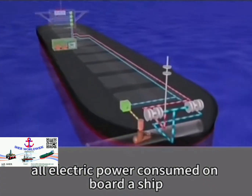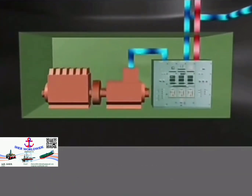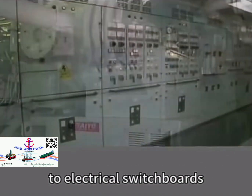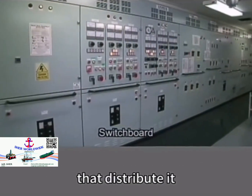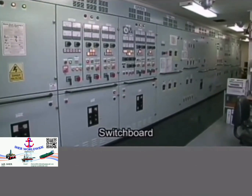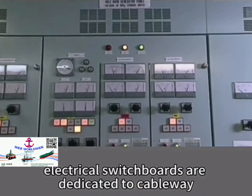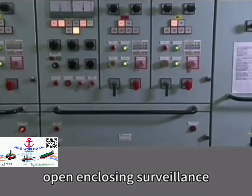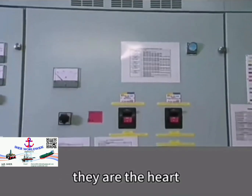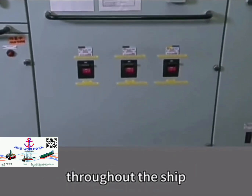All electric power consumed on board a ship is produced by onboard generators. Electric power is transmitted from the generator to electrical switchboards that distribute it to a variety of installations and equipment on board the vessel. Electrical switchboards are dedicated to cableway opening, closing, surveillance, control, and protection. They are the heart that ensures stable and safe distribution of power throughout the ship.